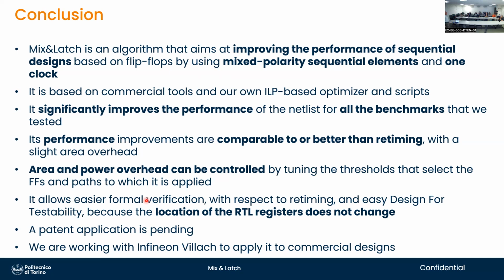Any further questions? Yeah, so when you're simulating different process corners or doing Monte Carlo, when you add inverters into your clock path, or if you have extended wires to delay to introduce clock skew, does that have much effect on clock tree synthesis? Does it make it harder?